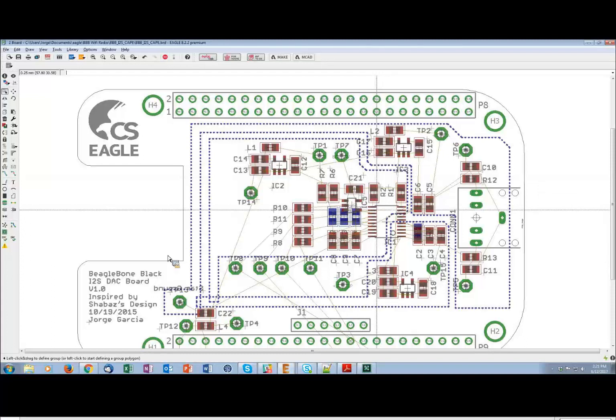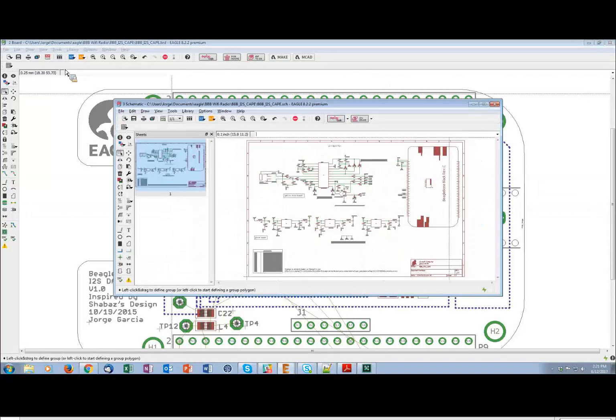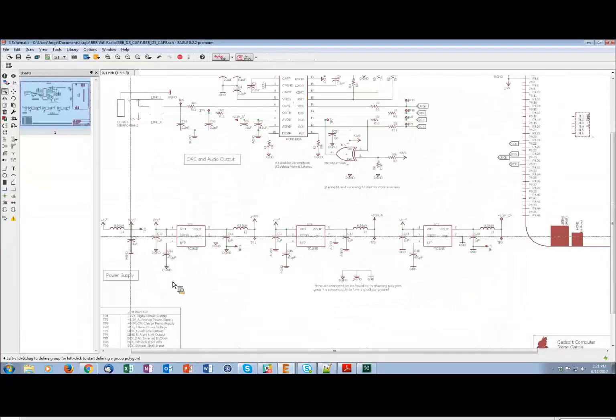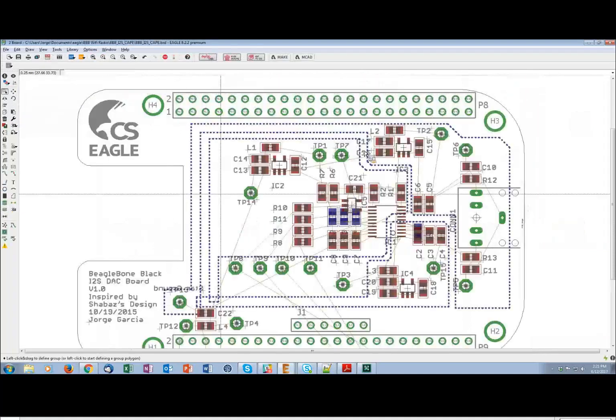we'll see the three power supplies. Okay, and in this architecture they all come back to a single point. So what this allows us to do is try to keep circulating currents within the same signal. So currents that are noisy, for example a charge pump power supply, that tends to be a little bit noisier than what we want to have interfering with our signal chain.